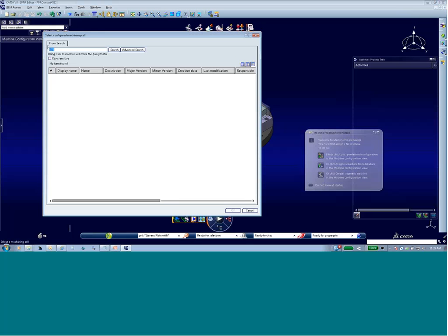So this lets me do a search for this machine. So again, all I need to do is enter a part of the string that I want to use. You can use wildcards anywhere inside the string, before and after the string. I can do a search for that. So it found one machine that matches this. It happens to be a Morisiki NMV5000. And so when I say OK, it then brings that machine cell in from the database.